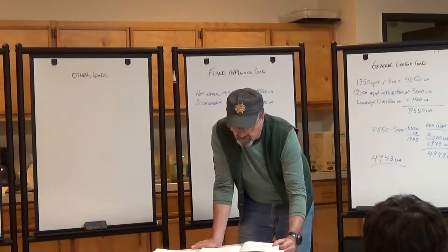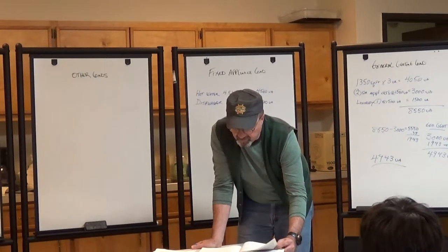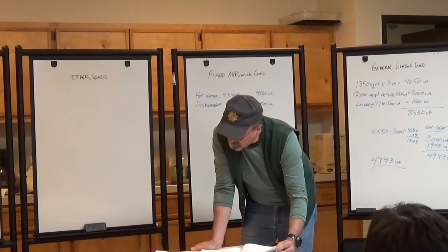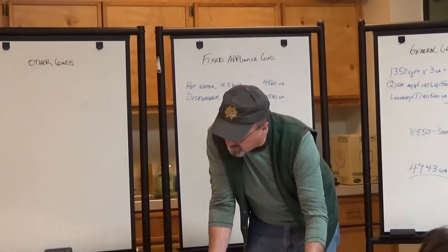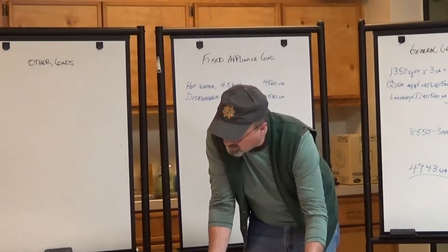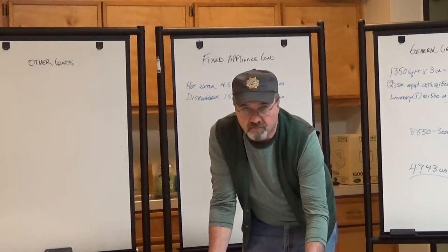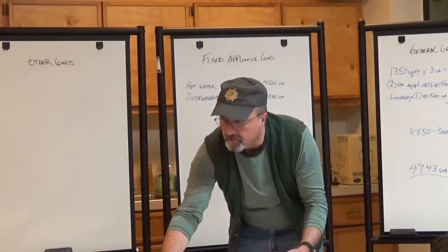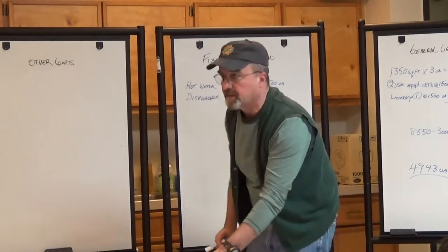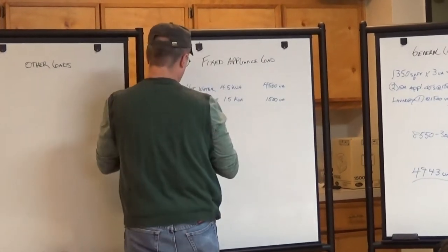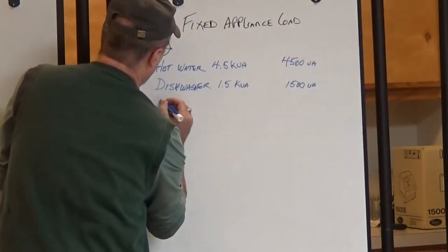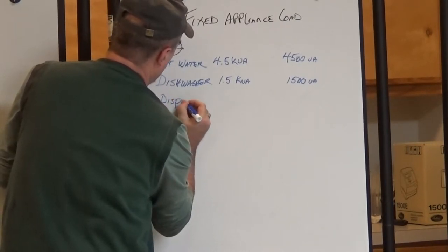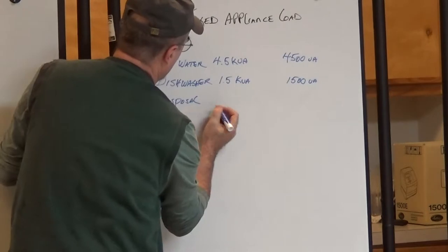Okay, so we have 9.8 amps, and we're looking at 120 volts. So what is the VA for that motor? Somebody figure that out? 1,176.